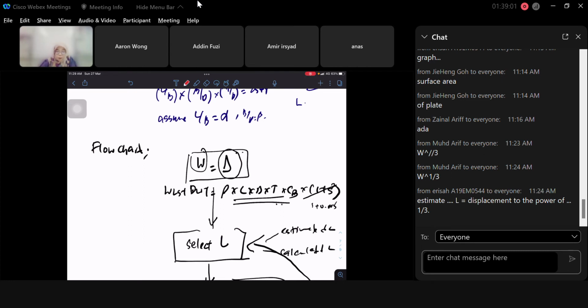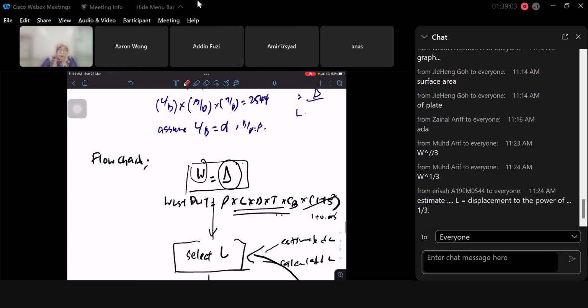If you're coming back to your owner's requirement, you actually start from the owner requirement before you start with the governing equation. So this is not part of the problem anymore. This is the real process of determining the main dimensions. So you start with the owner requirement. You have this ship type, you have this DWT, and you have the speed. From those owner requirements, you have DWT. So this is given to you.